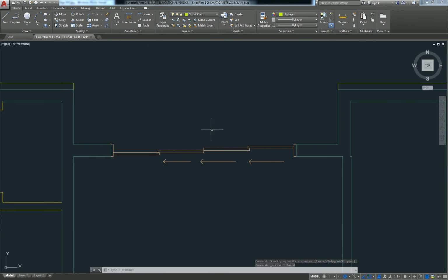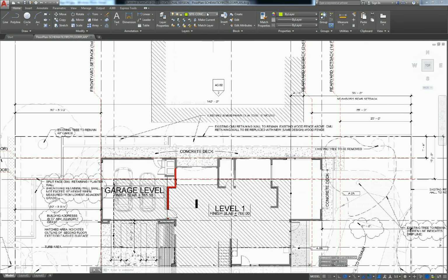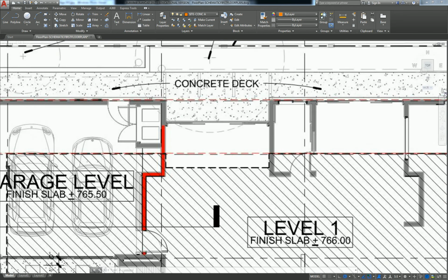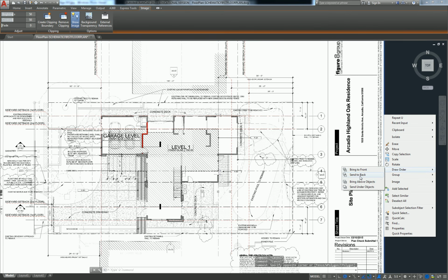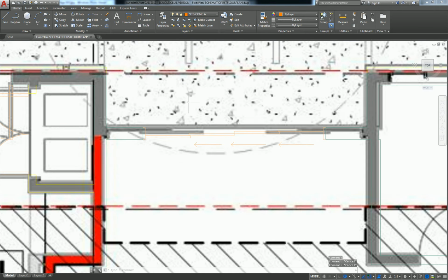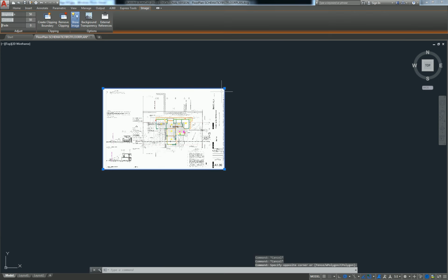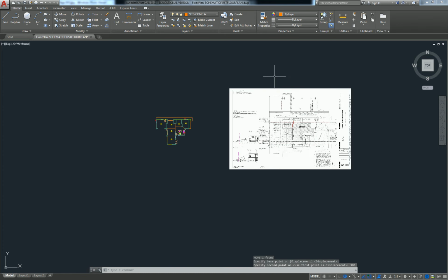So this element needs to be treated before we can create an effective hatch pattern. What I like to do generally is just use the edge of the concrete. So I'll just do site concrete. Oh, it's in the front again. Let's do draw order, send it back. Good. Site concrete A, so I'm going to draw a line across here. If you ever need to, you could put the image on a layer and turn the layer off, but sometimes I think it's easier to just move the thing and pick an even amount. So if I just move it over 300 feet, that's fine.